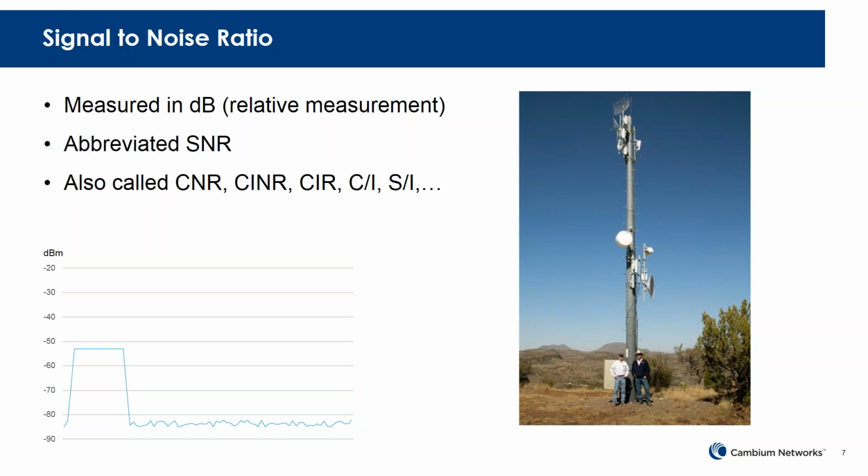But dB, just decibels without the M, is a relative measure. And we measure SNR, or signal-to-noise ratio, in dB. And so the idea is, how much stronger is the signal over any noise that I may be hearing as well? And so if you had a signal-to-noise ratio of 10 dB, what you'd essentially be saying is our signal is 10 times louder than any noise.